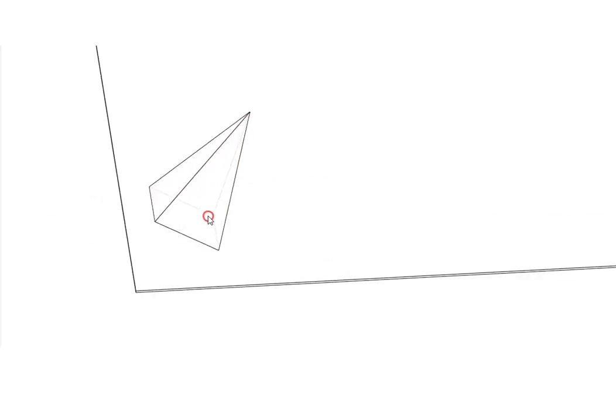And one more thing, when we look at this solid from the top, you could see it looks quite different than when the axis was perpendicular to the HP. Here you could see that there are only 3 faces. The 4th slant face on the other side is completely hidden, and the edge with respect to which it was tilted is also hidden. So this is how it looks.